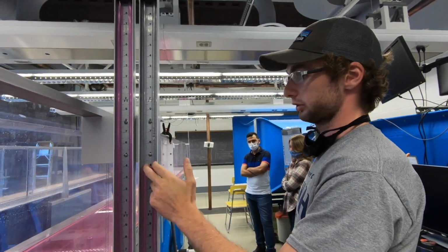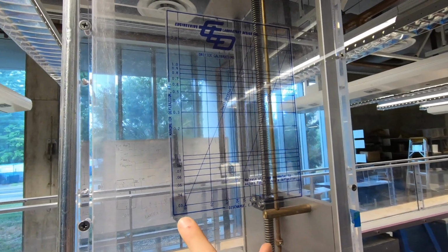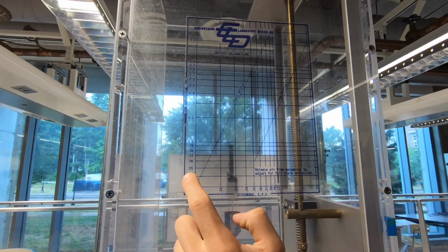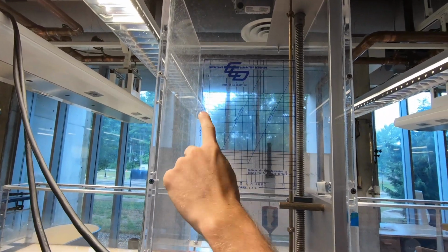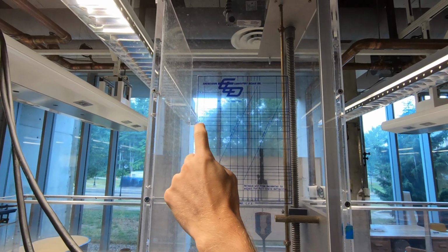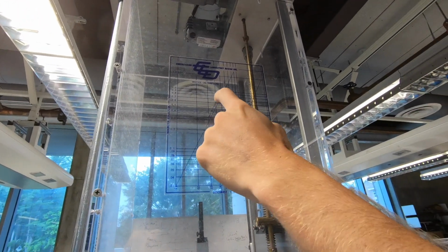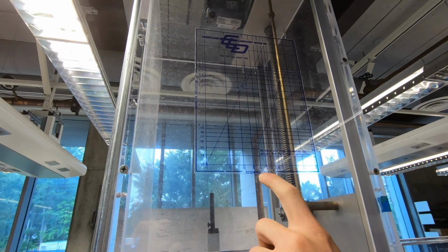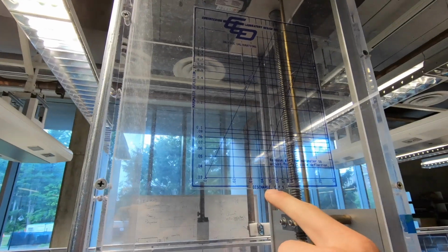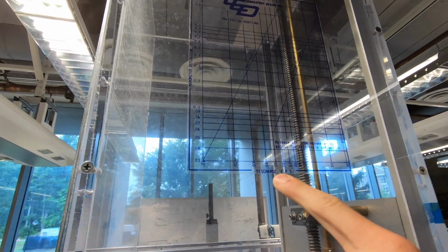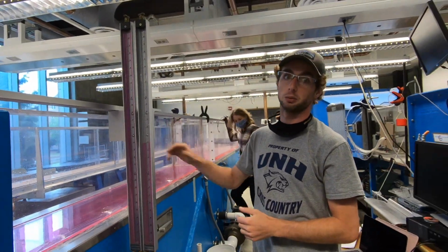We're going to be using those figures and looking at them on this figure here, which has a logarithmic deflection on the y-axis. So if they're 1/2 foot, we would follow the 1/2 foot deflection over to the small orifice curve, and we follow that down to our logarithmic flow axis. So for example, 1/2 foot would be approximately 0.05 cubic feet per second. So that's how we get our flow for the data sheet. We're also going to be recording the water height for data.